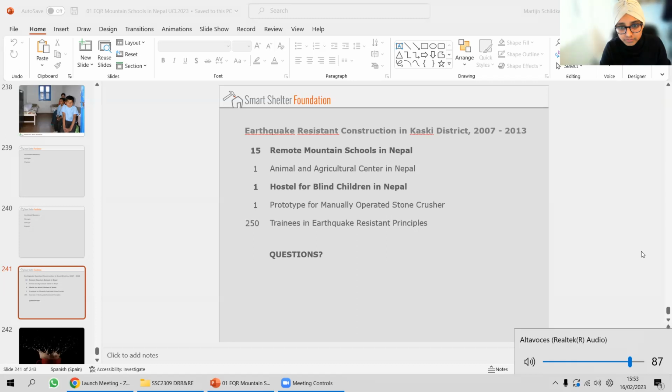So the first question was, in the final picture of the school, where captions were written on the walls, there was vertical encasement shown at the side of openings. So I want to confirm, did you provide the vertical reinforcement or encasement to the school? I have seen it around the openings.